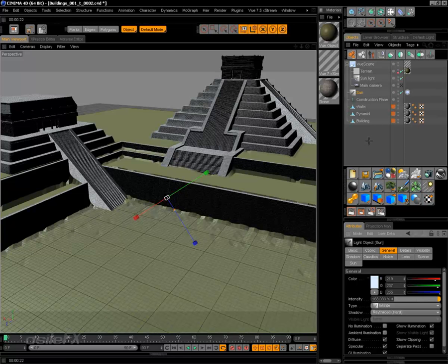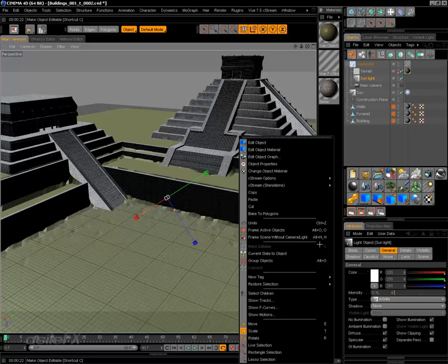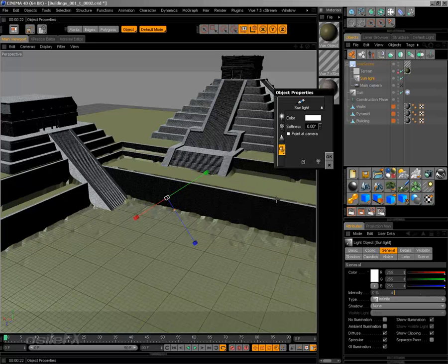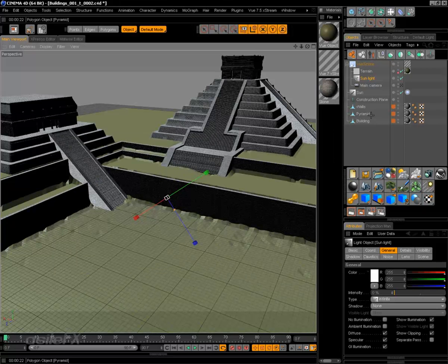If you're using RGB, really whatever color method you're using, although view only has certain levels of color that are available, so you have to pay attention to that as well. I'm using just the RGB mode. So just going to the object properties and editing the sunlight color, we can set it to that color. Click OK. And this still isn't showing up within the scene.